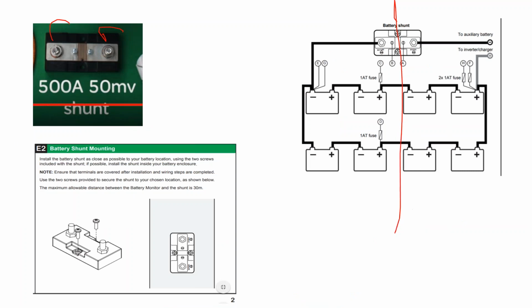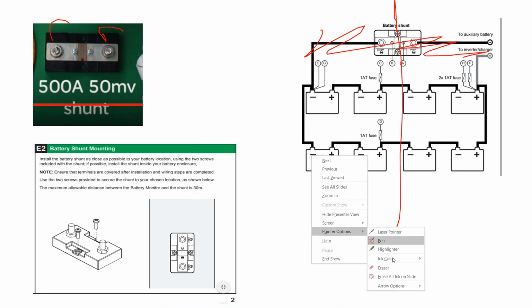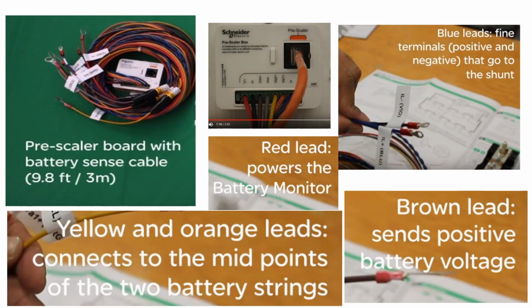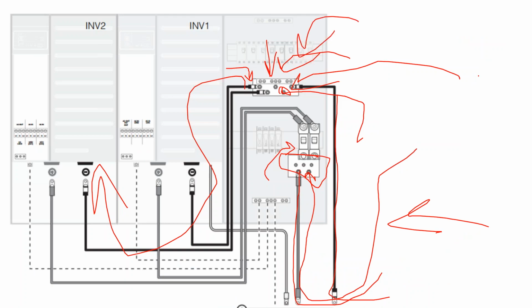And so actually it was both of us being dumb. The point was, we could just ignore this stuff right here. So we have our 2 battery circuits running back to our inverter, circuit 1 and circuit 2, and we ended up just double lugging them onto the shunt, and then double lugging them off of the shunt, and then running to that bus right here. So it really wasn't an issue. There was just no field instruction manual from the inverter manufacturer to offer that guidance.